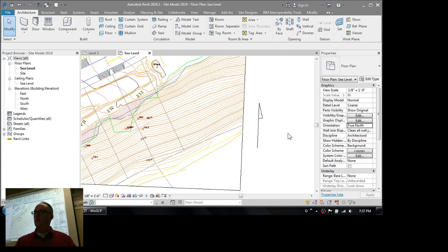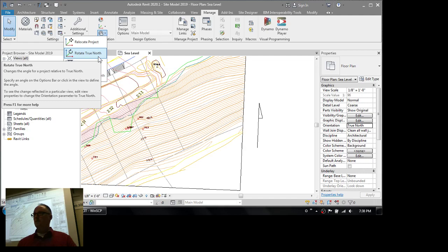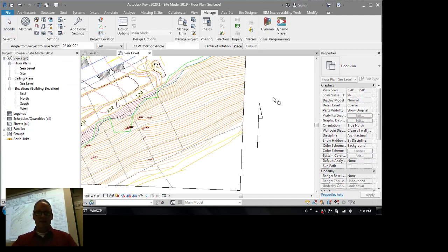Okay, so what I'm going to do, folks, and you'll have this on YouTube, so if you're losing track right now, it's not a big deal because you'll have the video to check it out later. So on the Manage tab, from the same drop-down menu, find Rotate True North. And so now again, what you need to do to start the rotation process, hit the space bar.